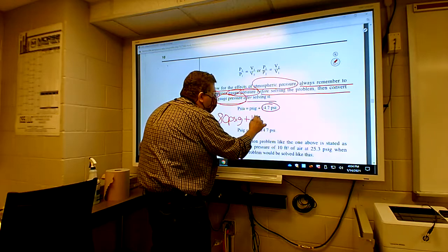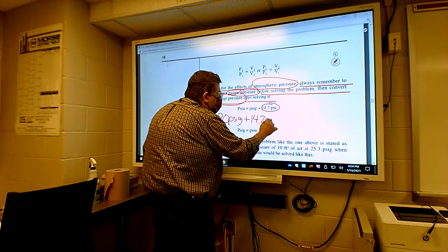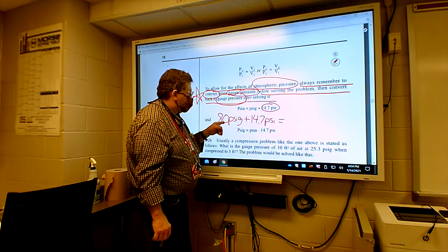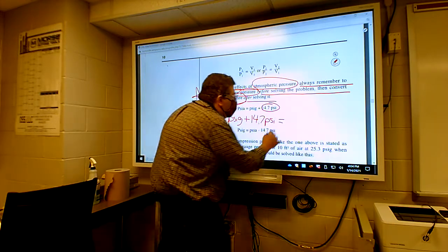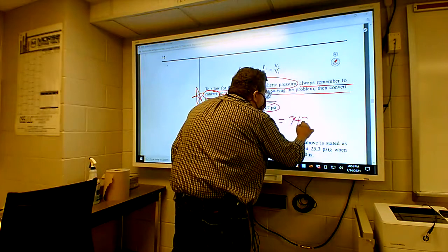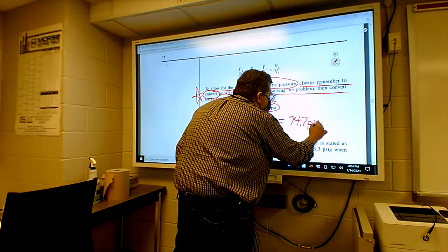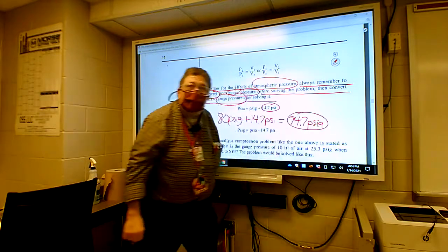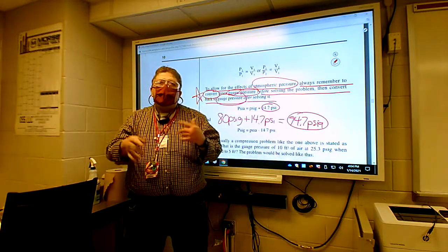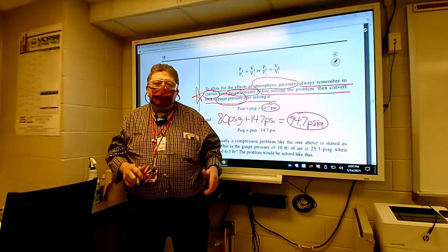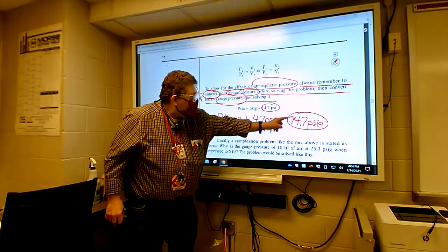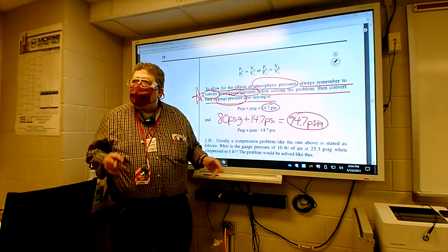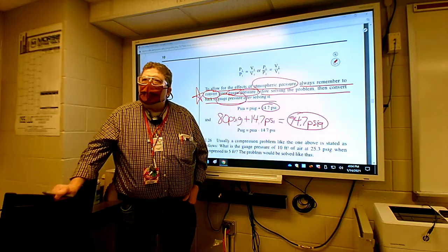So if you add 14.7 to that, what do you end up with? 94.7. That's the number that you're going to do the calculation with. When your calculation is finished, then you're going to go in reverse order and take that final number after it's changed, and you're going to subtract the 14.7 and go right back to gauge pressure.